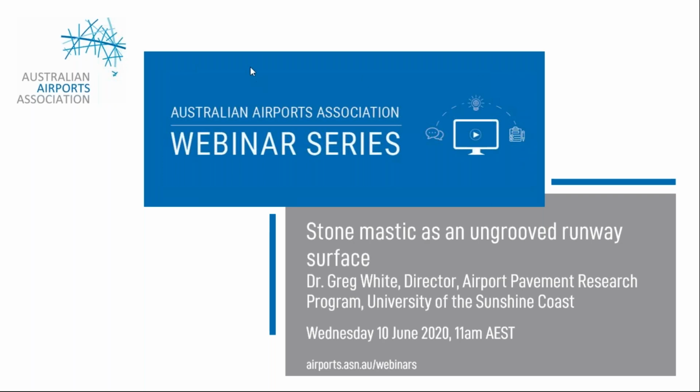I guess the reality is we'll only know, but certainly the surface at Latrobe, which was 5 years old, I didn't test it, but visually it looked like it had plenty of texture in it, although that's only lightly trafficked. And certainly the apron at Cairns Airport, which is 20 odd years old, is probably getting closer to 2 millimeters texture depth by now.